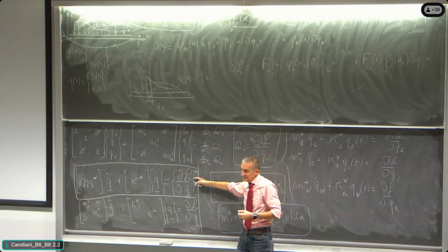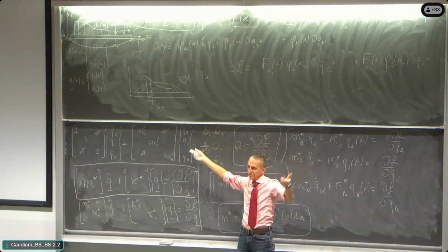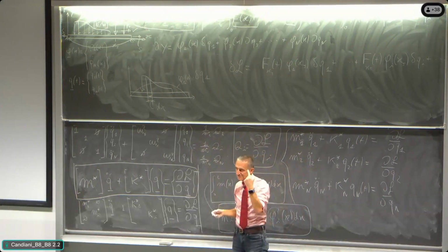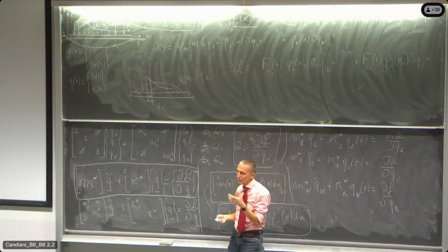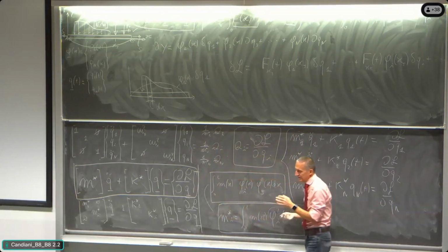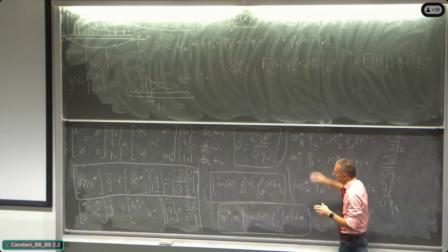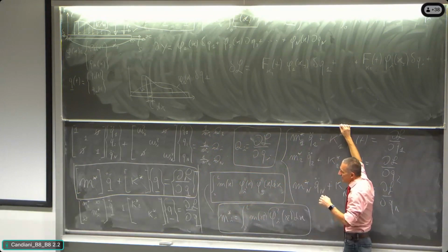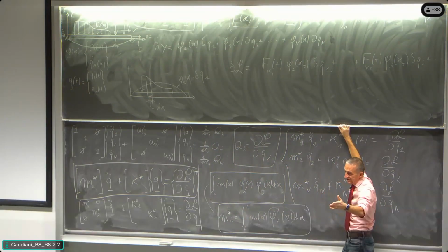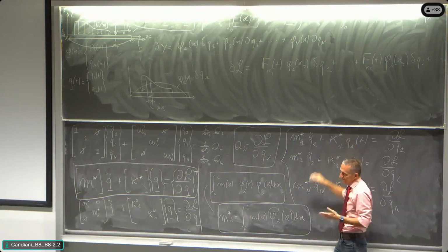So it means that in the first row I will have the partial derivative of the total virtual work with respect to the first delta q1. And in which way do I do all of that? In which way do I write the partial derivative with respect to the variable qi? Making null the others and just dividing by delta qi.